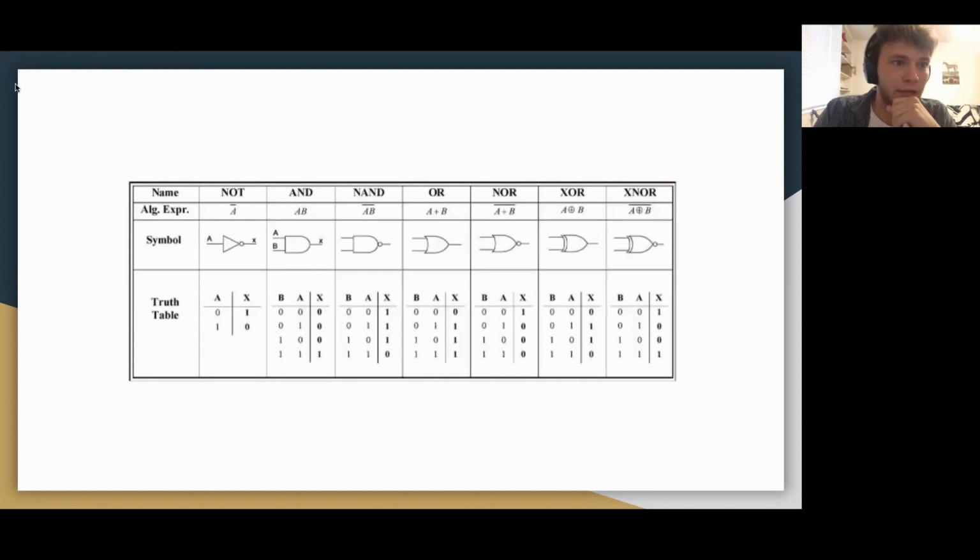First I wanted to show you some Boolean logic. And if any of you have coded before or looked at schematics, maybe you've seen some of this. But if you've not, I'm going to go over some of the basic ones. The one we're going to focus on a lot today is this AND gate. So let's say we have two binary values being 0 or 1. An AND gate requires you to have both be on, so both need to be 1. And you can see X would be your outcome, of course, here. So if B and A are both off, you're not going to have it. If one's off, one's on, you're not going to have it. One's on, one's off, not going to have it. Both have to be on for an AND gate to then produce output X.